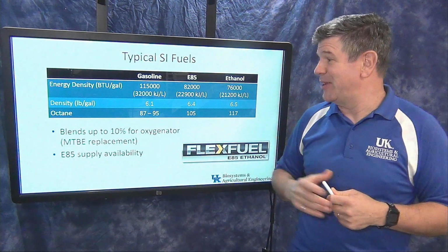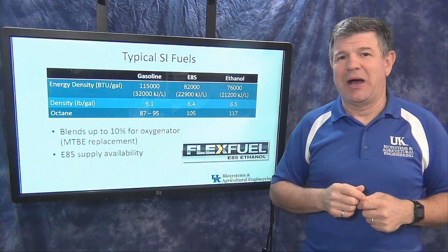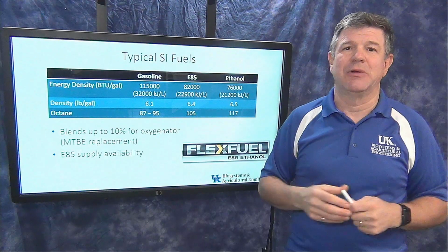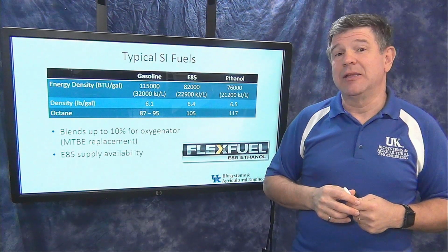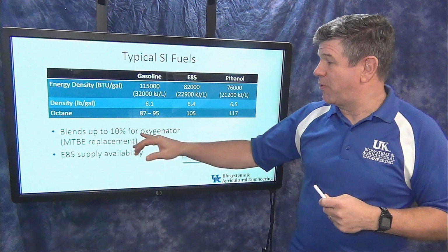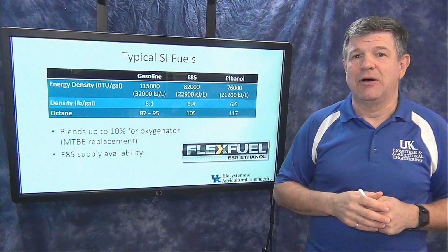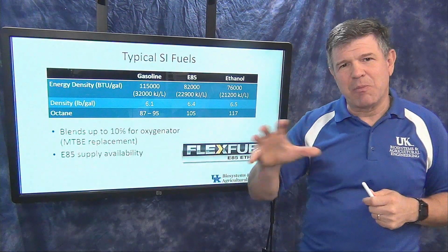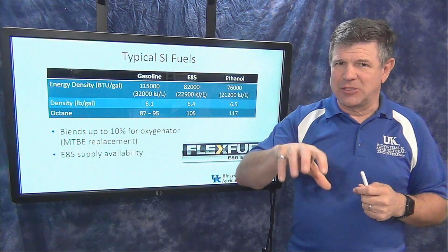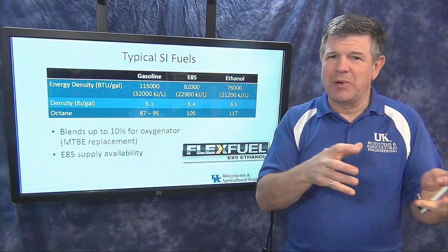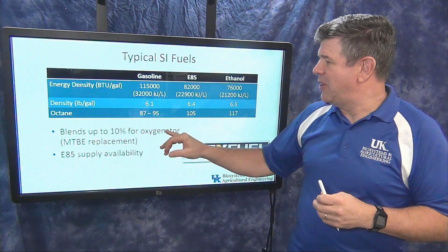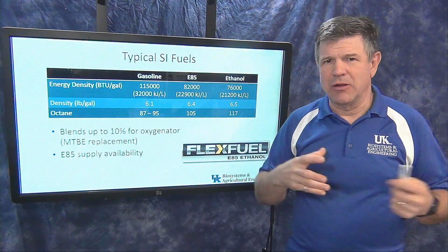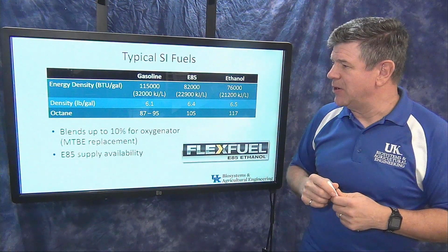So that's what we would say, that typical gasoline that you buy is E10. Now, we rarely do that because that's kind of like the common supply. That's what everybody gets. But understand that gasoline supply is probably 10% ethanol, and we do that as an oxygenator. We're going to come back when we look at some of the stoichiometry and the chemistry combustion reaction. We'll see why that is important, why we have ethanol in there as an oxygenator to put oxygen in the fuel. And that'll be pretty neat when we see that.